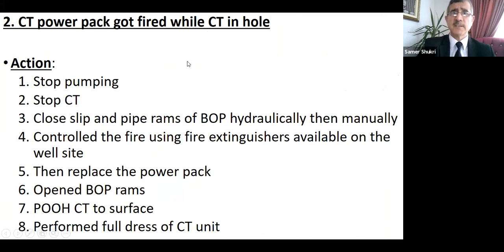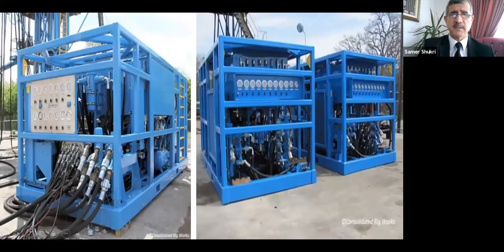We were working, and suddenly this power pack got fired because there was a hydraulic oil leak here, and we were doing a clean out. You have high temperature in this case, and the time was summer, and the desert temperature was 45 degrees centigrade. High temperature and oil, maybe sparking also.